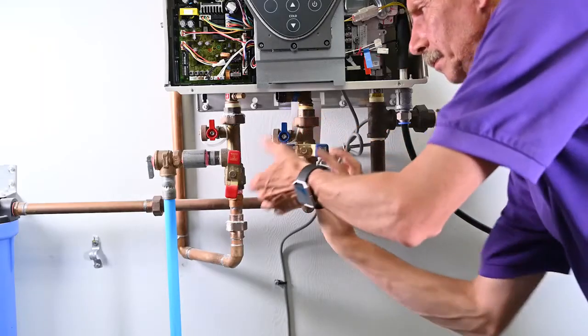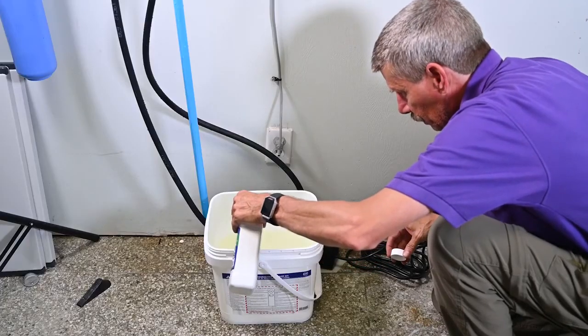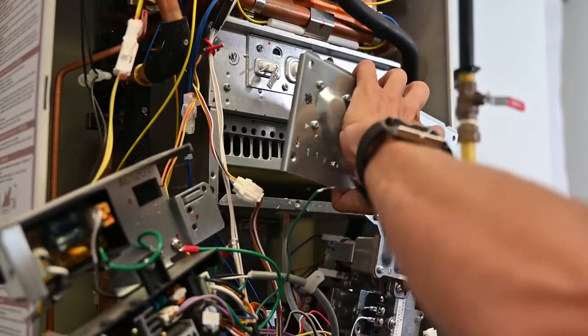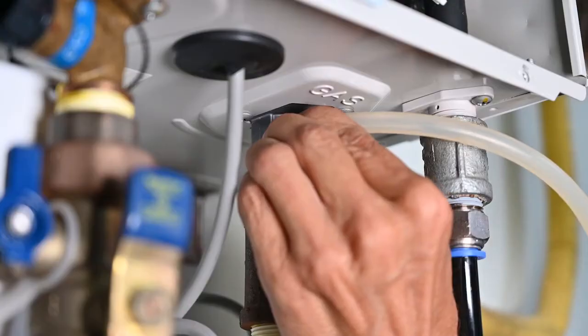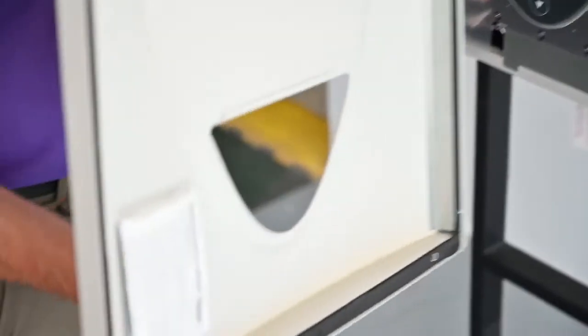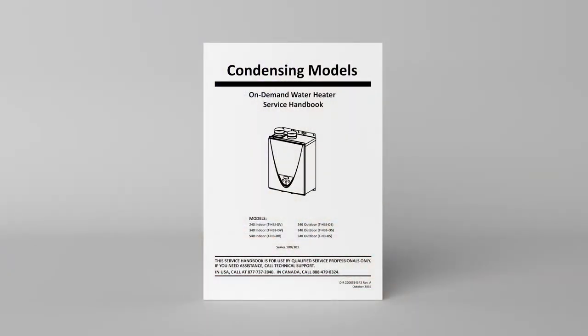Next, the unit should be drained and descaled using a food-grade acid such as vinegar. Finally, the burner should be inspected for dust, lint, grease, or dirt, and the inlet gas pressure should be measured by a licensed professional. Step-by-step instructions for this procedure can be found in the service handbook.